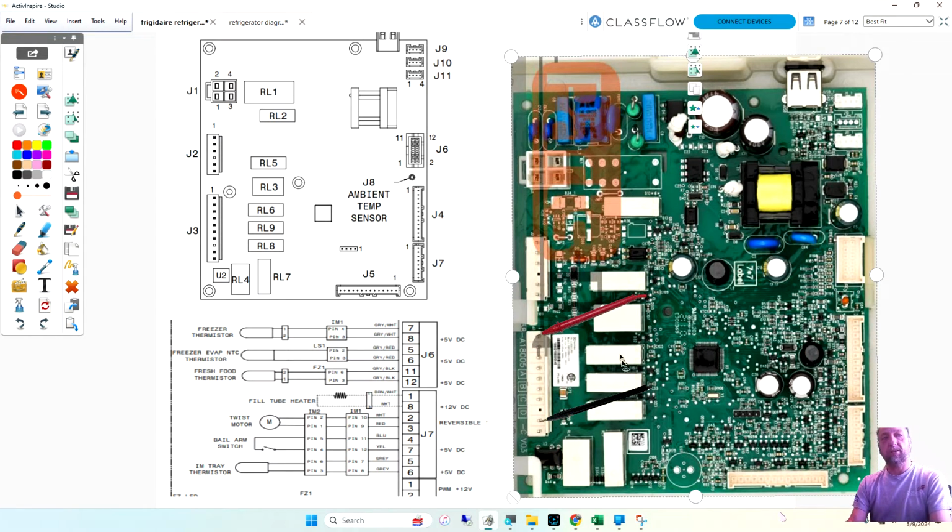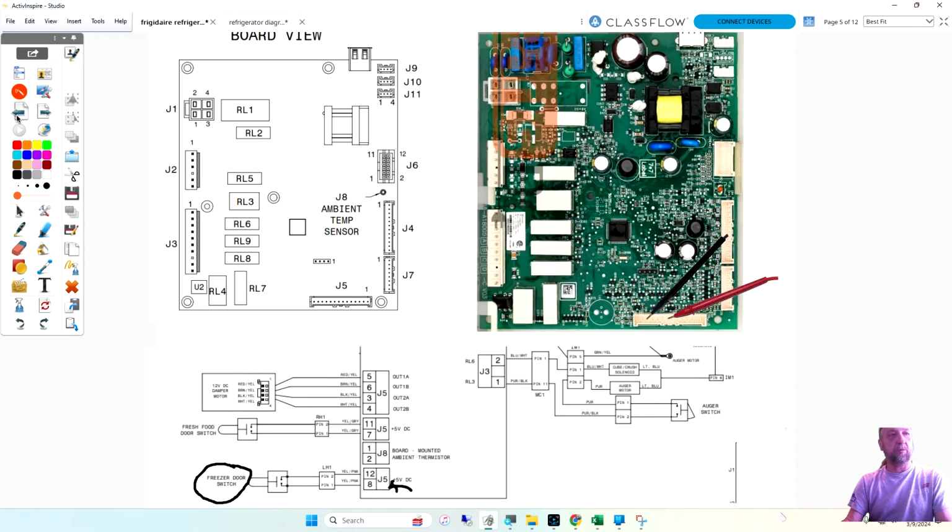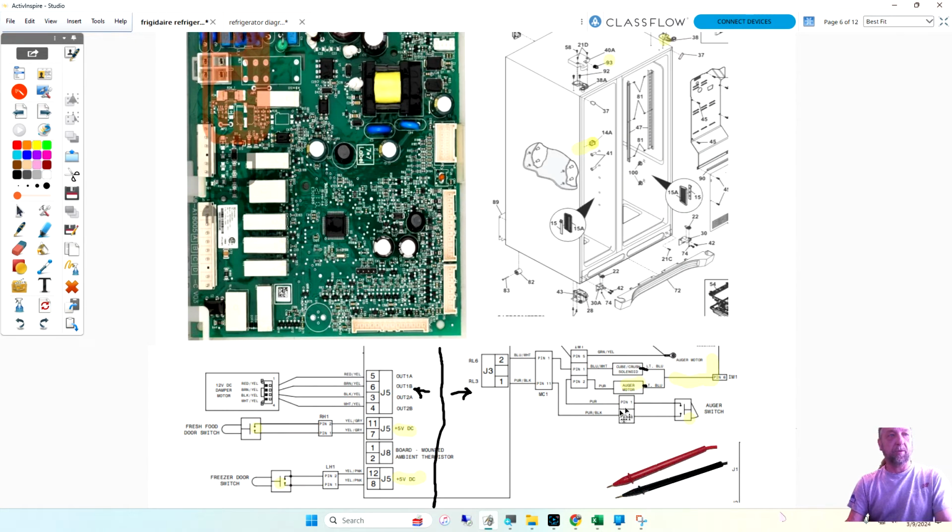And these little white boxes are the relays. So let's just say, for example, this one here is 9, or whatever number, 6, 9, 8, whatever. I don't know what number does which part. But if you really want to know which one of these relays was going to pin 1 and 9, if you flip the board over, you can follow the traces on the board and see which one goes here and here to power that. But if I have 120 there, I still have to do what to determine my fault in this circuit?